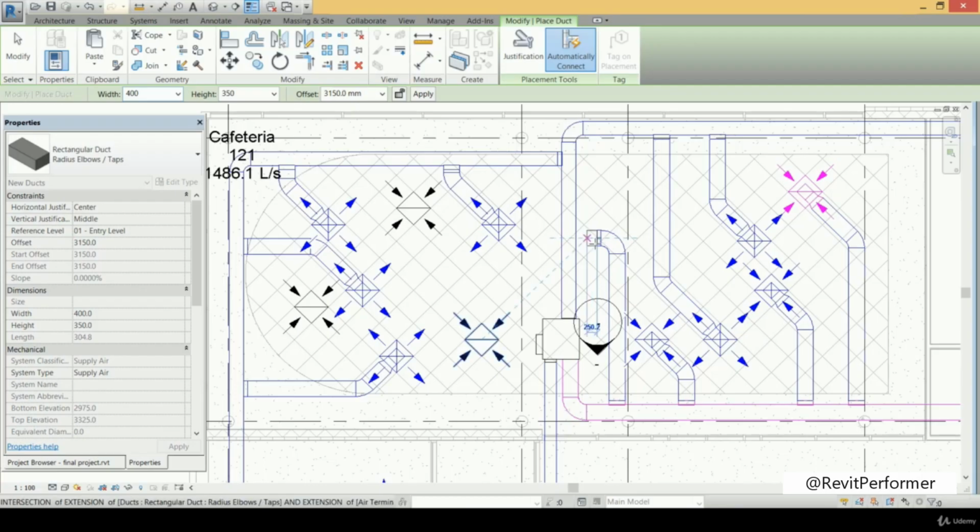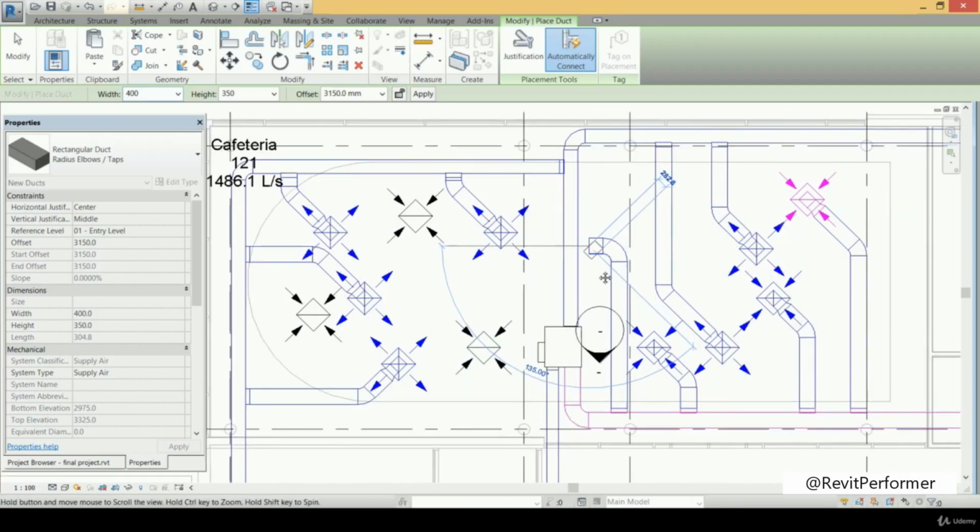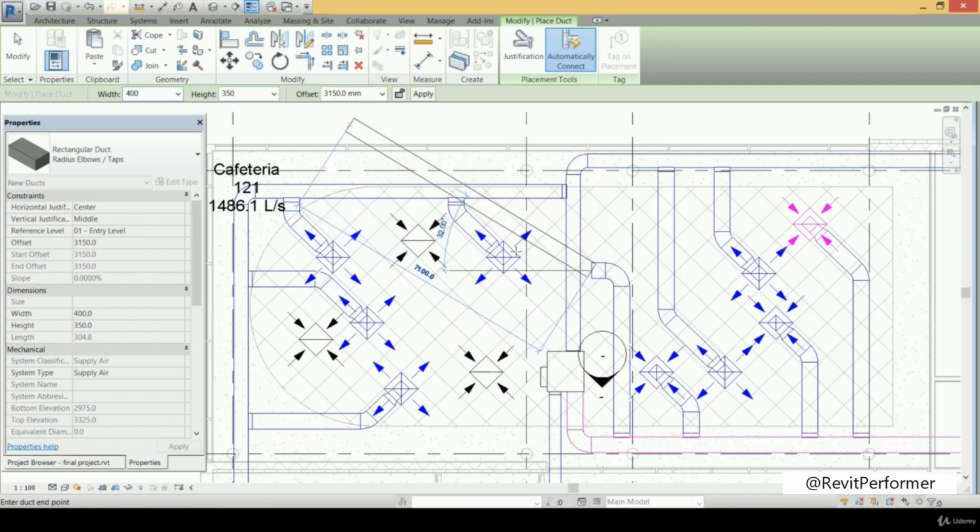And then let's move also a little bit forward. And now let's decrease the offset of that duct to overcome the supplying duct. So we need no interference between the return duct system and the supplying duct system. So we make it to be here 700 and go until that point here. But as you see, we will face that diffuser.